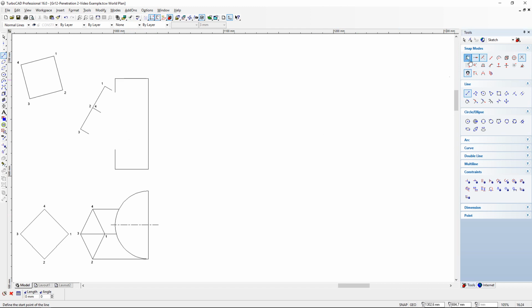Therefore, what we need to do is draw an angular construction line from the center of that pyramid at an angle of 30 degrees. So I have to go 180 plus 30, which gives me 210 degrees. And then from there, we draw another 30 degree interval. That means it is 210 plus 30, which gives us 240. And we also need to draw an interval to this corner of our prism where number 1, the top part of the prism, penetrates the cylinder.